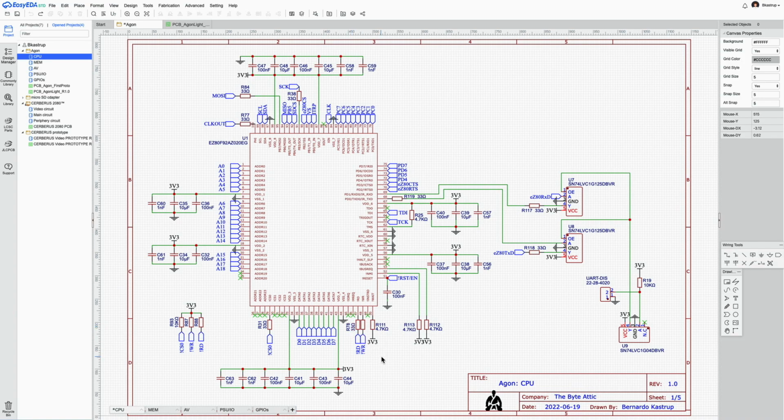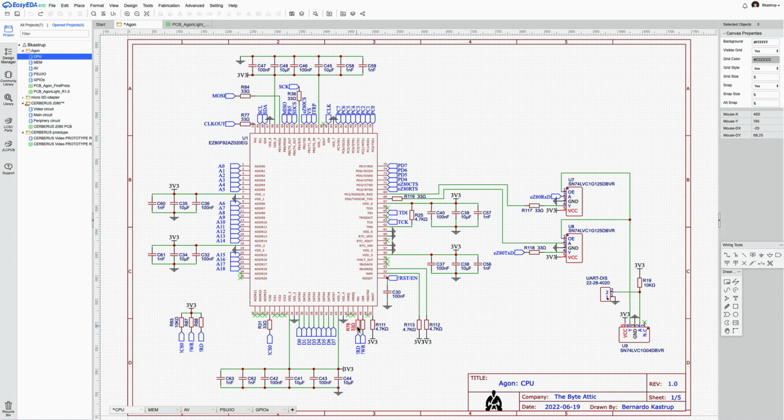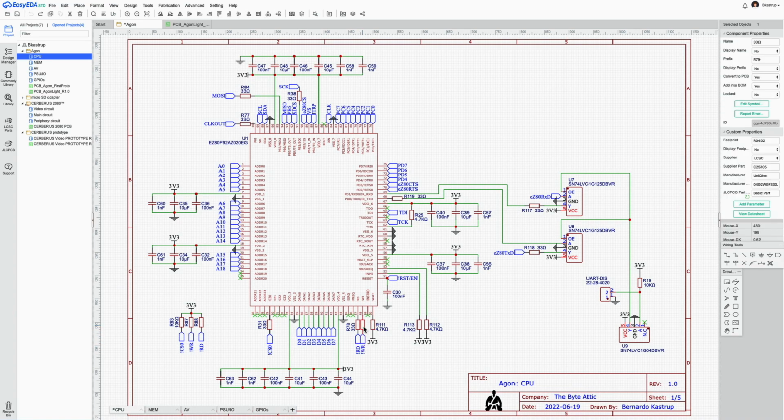And in practice, what that will mean is that the higher frequency components of these signals that will get reflected because of an impedance mismatch later on, they will get absorbed by these little resistors. These resistors, together with the normal parasitic capacitance on the board, will work as a low-pass filter and will absorb the higher frequencies and therefore reduce the amplitude of ringing. And for the control signals, this is important because you don't want the memory to get a false write signal and then capture whatever trash is on the bus before it actually should capture the contents of the bus. So, ringing could induce this kind of thing, and these are active low signals.